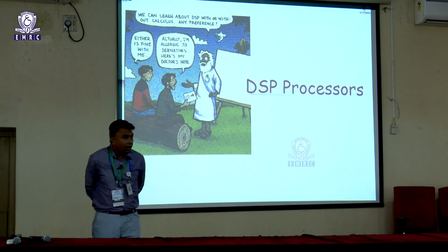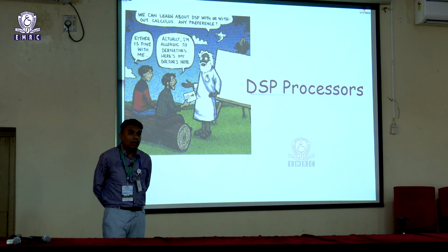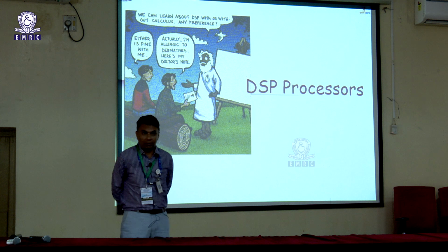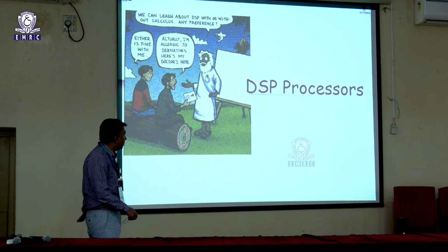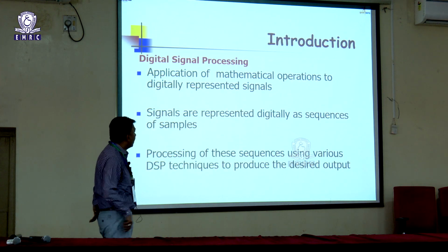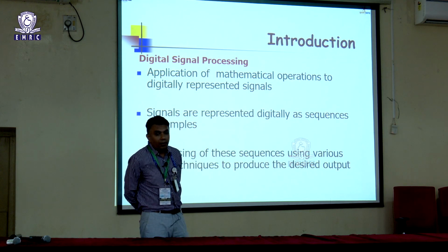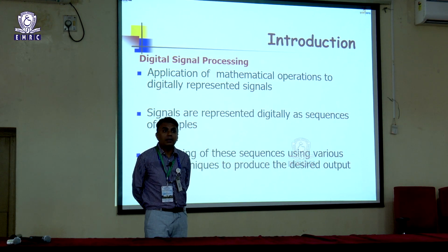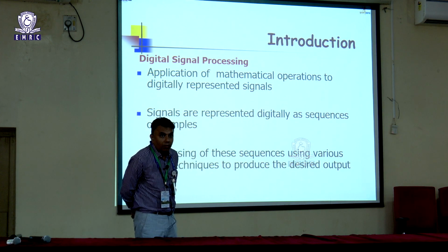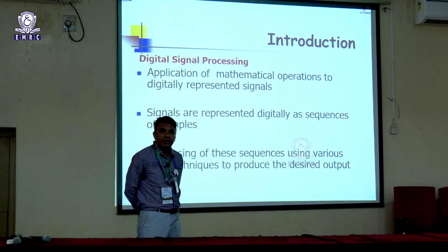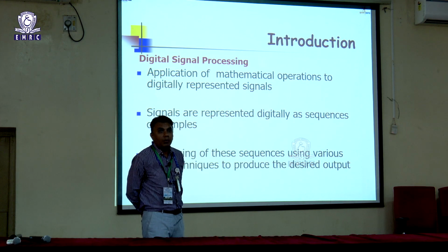Apart from that, there are some mathematical computing applications onboard where we also require a DSP processor. What is so specific about the DSP processor? They are required where we need a lot of mathematical computation, like FFT calculations onboard, or a lot of digital filtering. There we have a dedicated processor sitting, although we now have two options onboard.